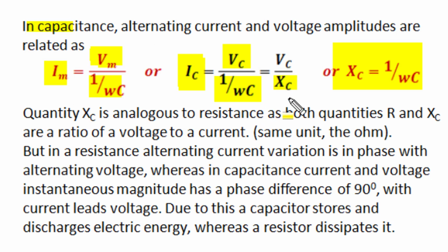So this property of current opposition that demands proportional voltage for current flow is not called resistance, but we call it reactance, and we can say capacitive reactance is that property of a circuit which opposes alternating current flow across it, and for alternating current flow demands proportional voltage but won't consume electric power. It only stores energy when voltage is increasing and releases the same amount of energy when voltage is decreasing.